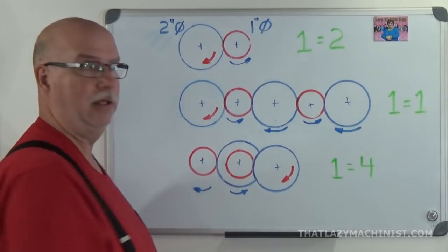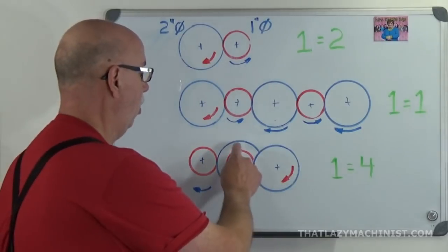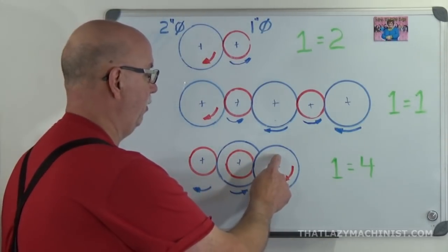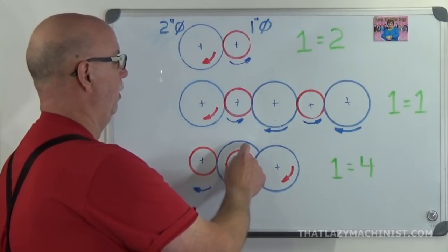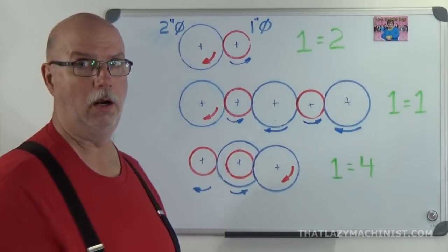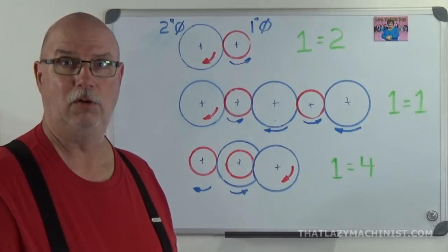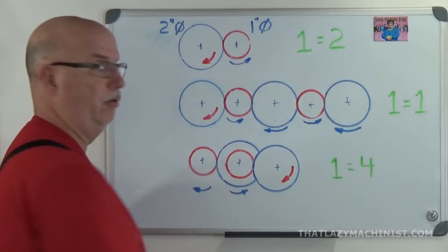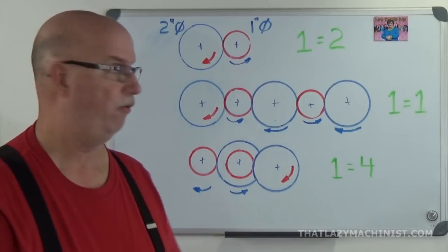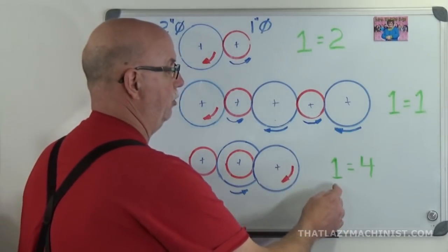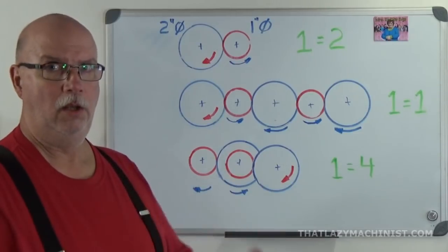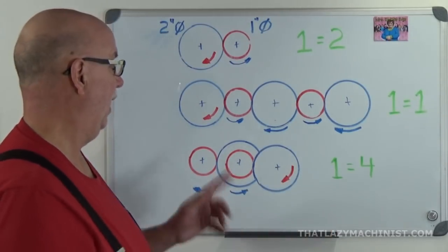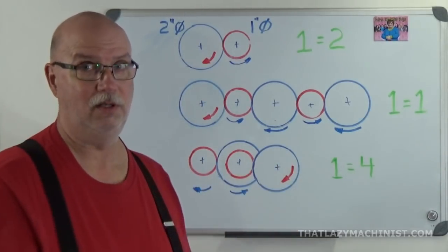Large gear, small gear, and we again have 1 turn to 2, so 2 turns to 4 with the same ratio, but we're at an advantage of 1 to 2 and 1 to 2, so that means 1 to 4, and that's my advantage, 1 to 4. Now we notice that I get a much greater advantage, and I use a lot less space.